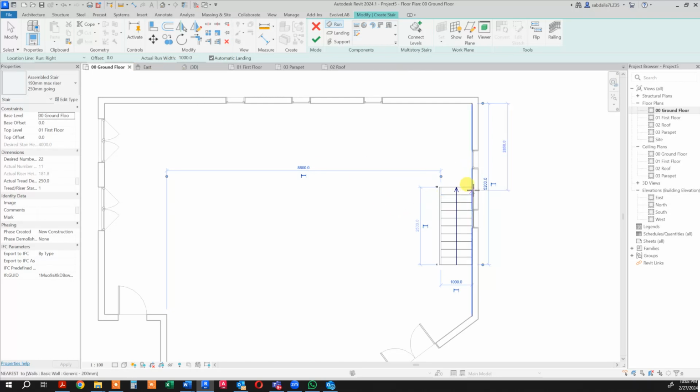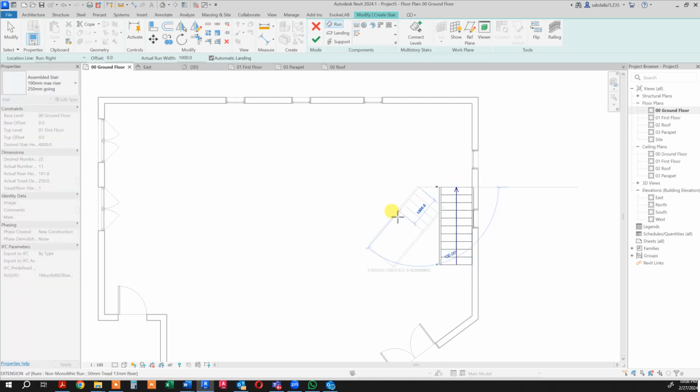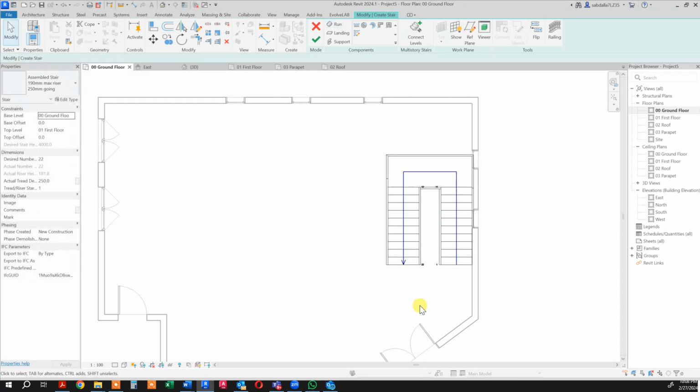So now I wanted to, before I use the left, right, if I stay to the right, it will stick here. So let's see, I want to do mine here, okay? Okay, good. So see, they're overlapped. So what I'm gonna do now, the line location change to left. And now I just have to go straight here and just finish up. It says 11 risers created, 0 remain. So this is my stairs. You go from here up there, okay? And then I approve it.